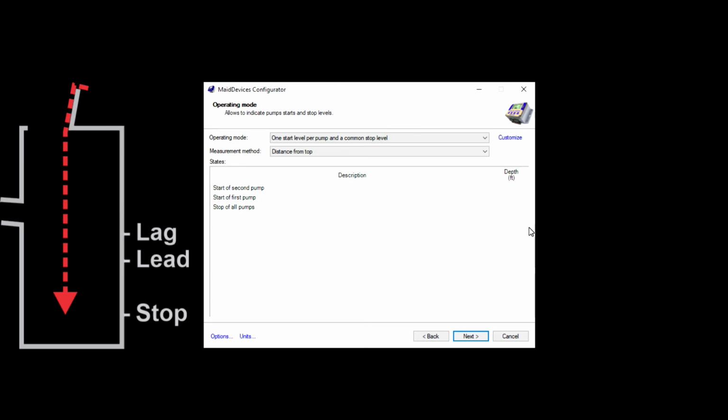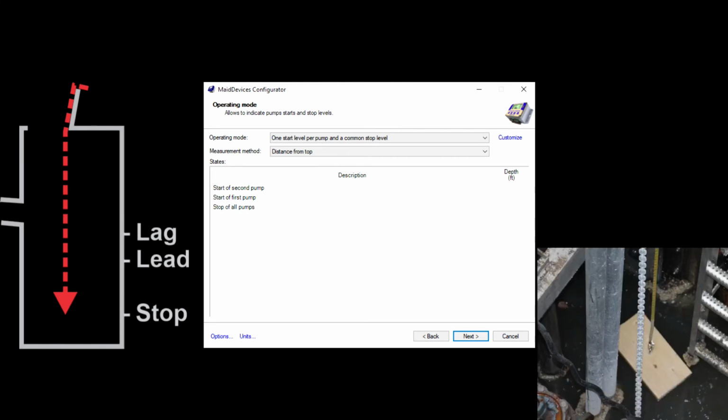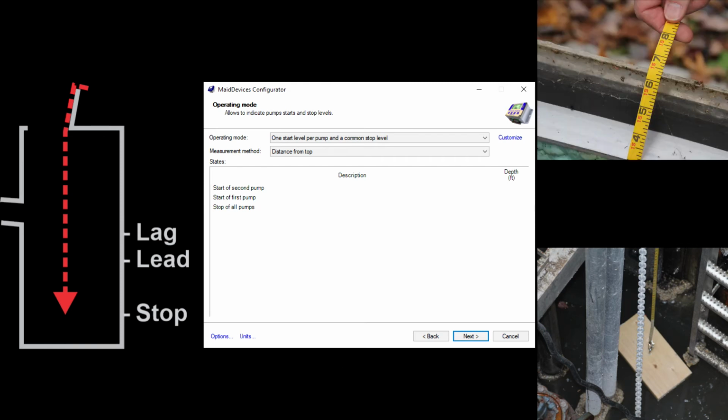Distance from the top of the well is the easiest to use for double-checking the measurement used or creating the first good measurement. A floating weight is attached to a measuring tape, and measurements are taken while the pumps are operating. Even if a level sensor is used, a measuring tape should be used to ensure that the sensor is giving an accurate measurement, since all Volucalc calculation results will be proportional to the accuracy of the measurement entered.